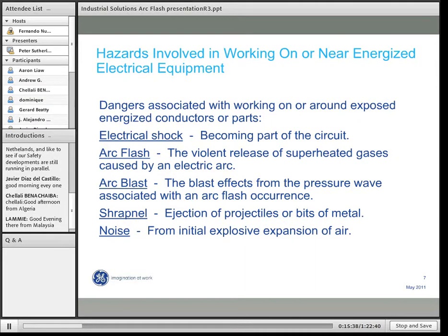There are many reasons for short circuits and other types of failures that will cause an arc flash, such as, for example, if a circuit breaker is attempting to interrupt a higher fault current than it's rated for, then the arc is not interrupted when the breaker is open, and you have another arc flash situation.